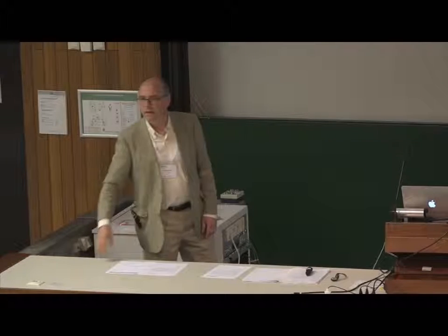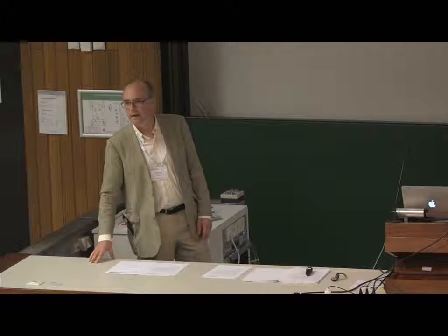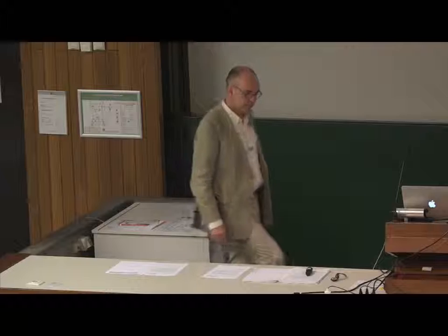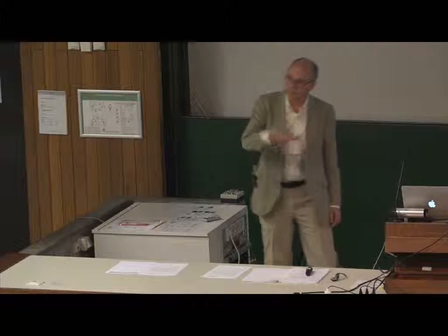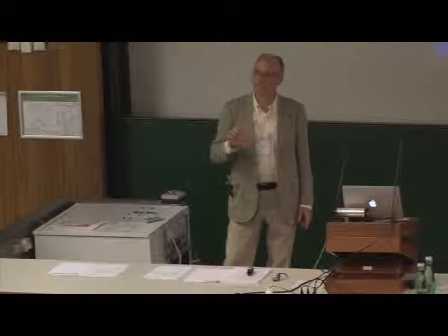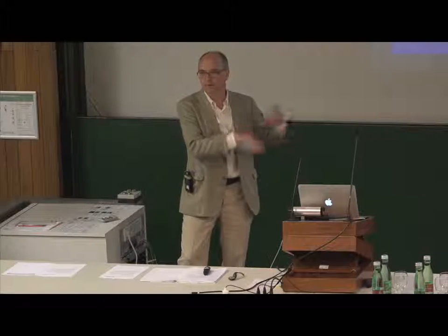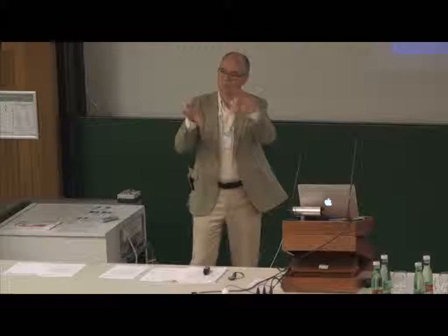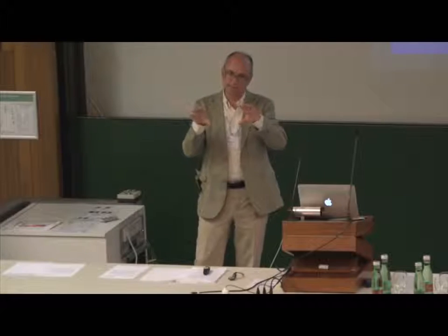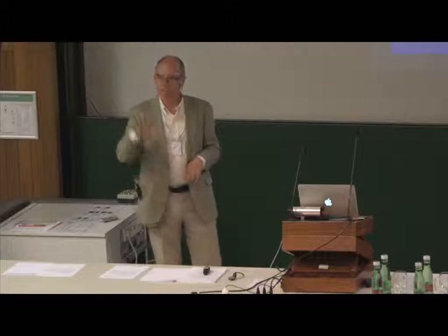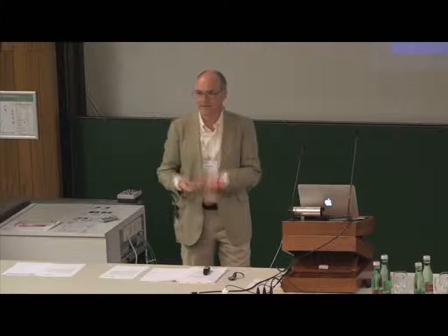So my question is about optimal control with constraints. Is there any exploitation possible of positive systems when you want to solve constrained optimal control problems? Yes, I mentioned the convex-monotone setting, and as long as you put convex constraints on the input, it will combine well with those convexity properties that are already present. But you have to watch out when you make compositions of functions, because a composition of two convex functions doesn't necessarily have to be convex. So it's easy to make mistakes that destroy convexity, but it's doable.